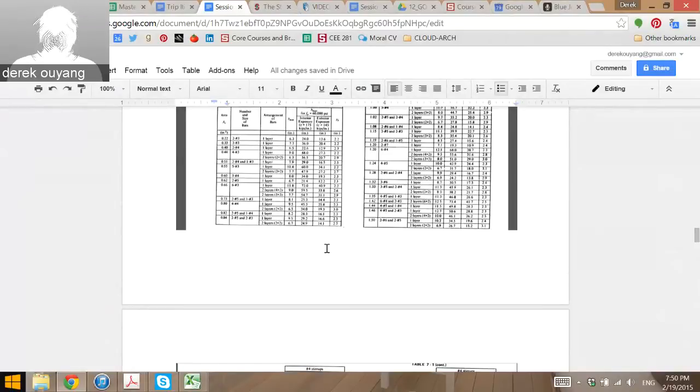The architect wants 10-foot ceiling height, right? And so you say, okay, well then if we're talking about a 12-foot floor to floor, then I only got 2 feet to work with. And that's the constraint on this. And you have like a T-beam, and then you have floor on the top, ceiling on the bottom, or space for ducting even, and you're constrained by this condition, right?